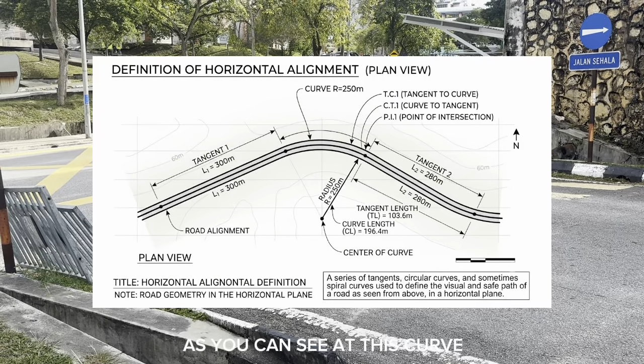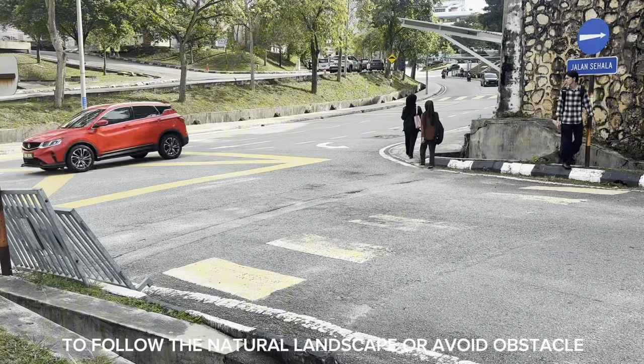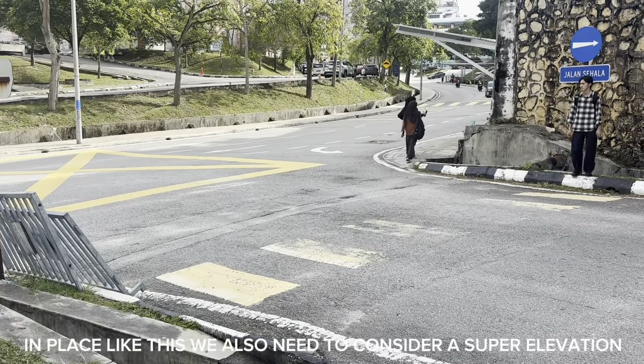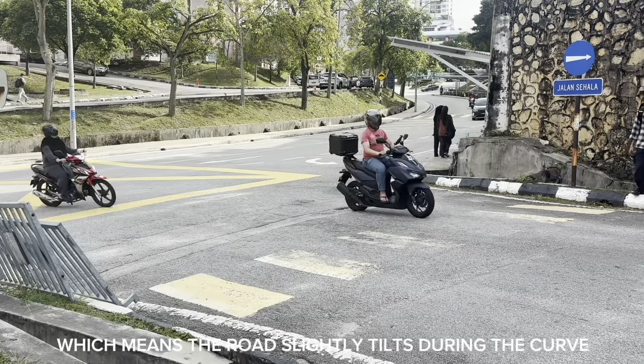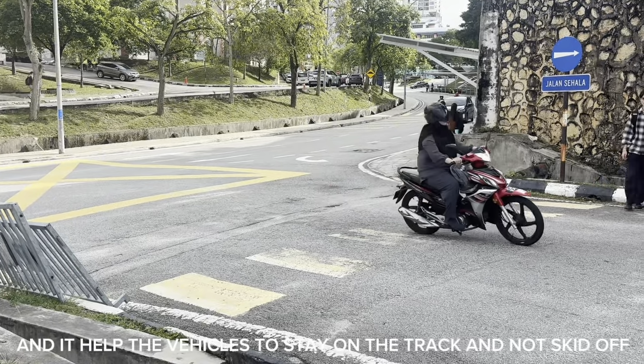As you can see, at this curved part the road is designed to follow the natural landscape or avoid obstacles. In places like this, we also need to consider super elevation, which means the road slightly tilts during the curve, and it helps the vehicles to stay on track and not skid off.